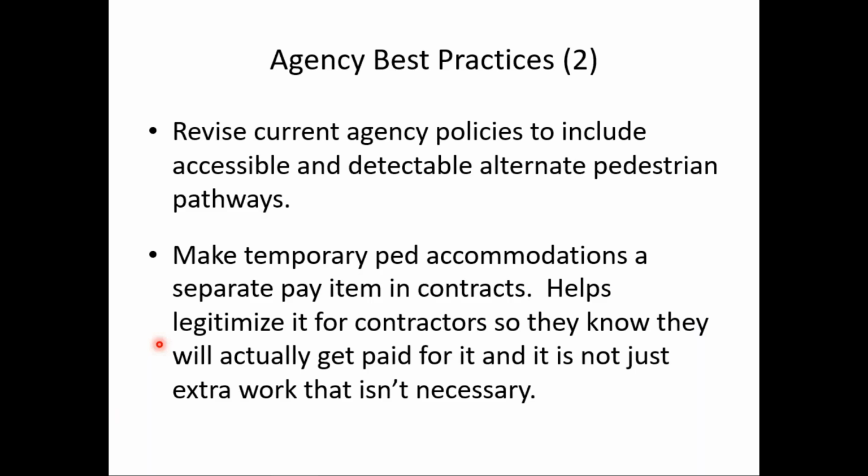And we had a question earlier about how to encourage contractors to do these things. I would suggest make these temporary pedestrian accommodations a separate pay item in the contracts. That helps legitimize it for the contractors so they know they'll actually get paid for it and it's not just extra work that isn't necessary.